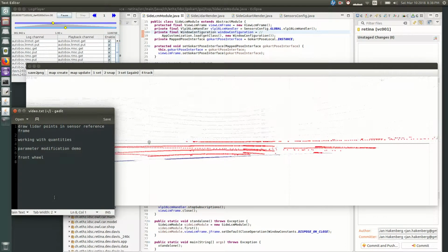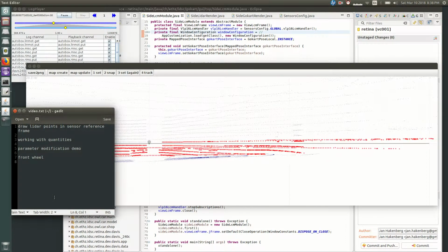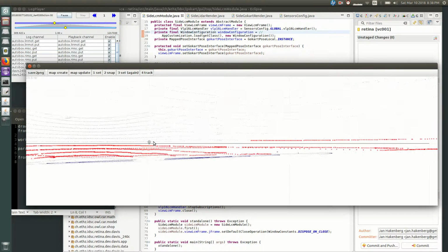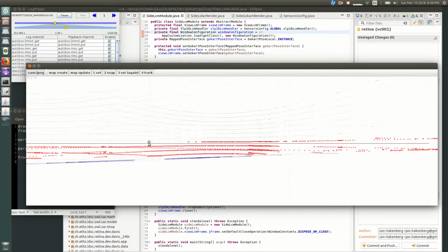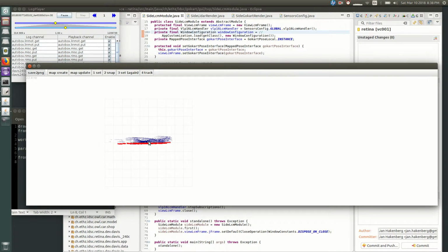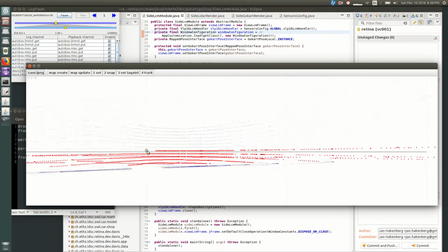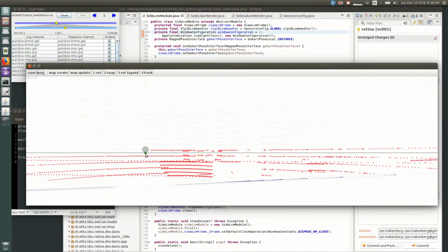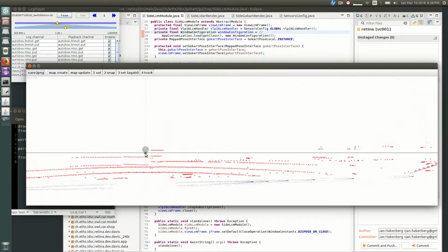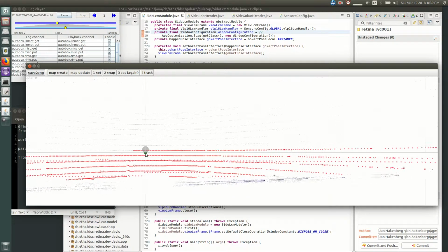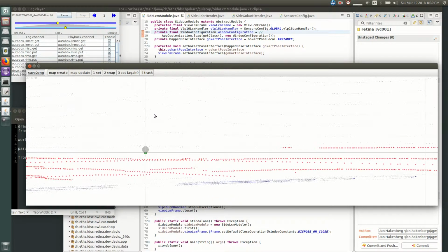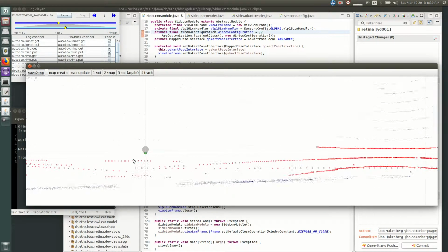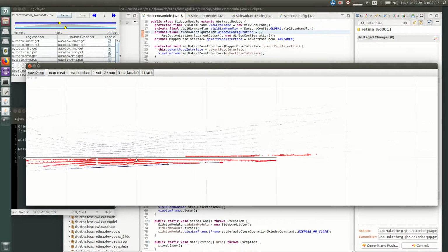The topic of this video is visualization. We are going to work with the LiDAR points. At the moment, the LiDAR points are drawn not in the correct frame of reference. This is the rear wheel of the go-kart, and the LiDAR points are drawn as if the LiDAR was at the origin here. So we have to move the origin of the LiDAR somewhere here, so that the LiDAR points are drawn accurately with respect to the true origin.